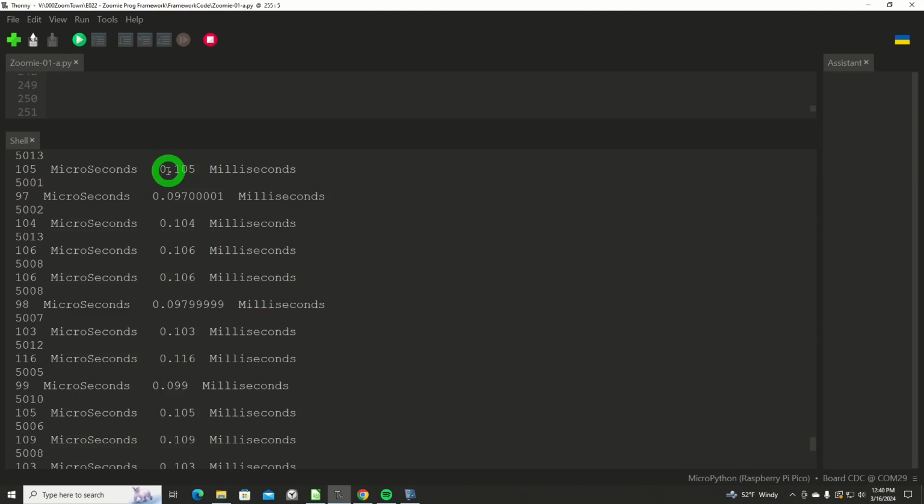Now you'll also notice that even though I added another 1/10 of a millisecond of time to the main loop, my main loop trigger is still running at 5 milliseconds. And that's what I mean by a deterministic loop. Everything that's in there, that loop has to run as close as possible to 5 milliseconds every time. And that's what we'll be focusing on for a good portion of this whole project, to make sure that happens.